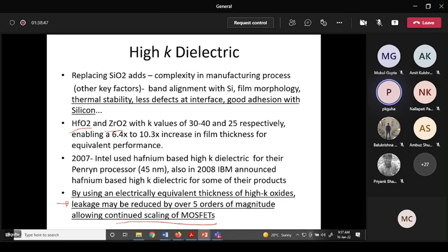But if you can't use high K material, then with the SiO2 we would have only a few atomic layers, which is very difficult to fabricate, and also very difficult to have a reliable gate oxide or reliable MOSFET, right?